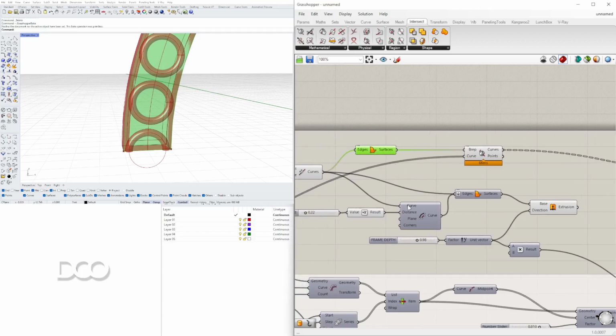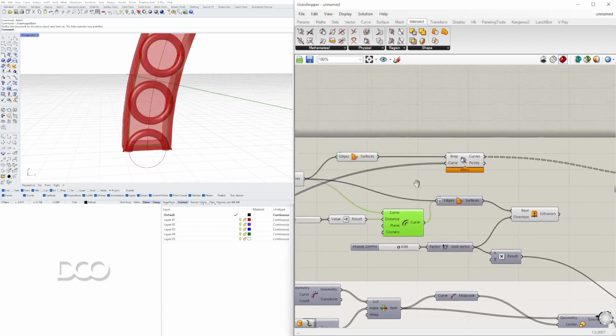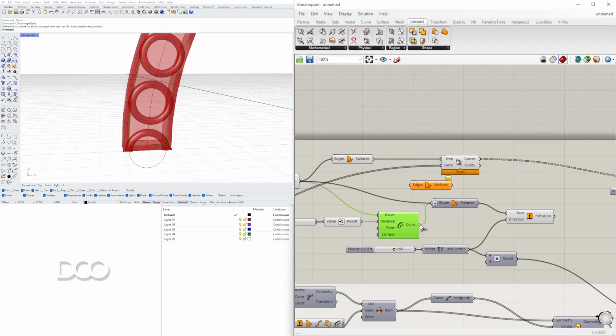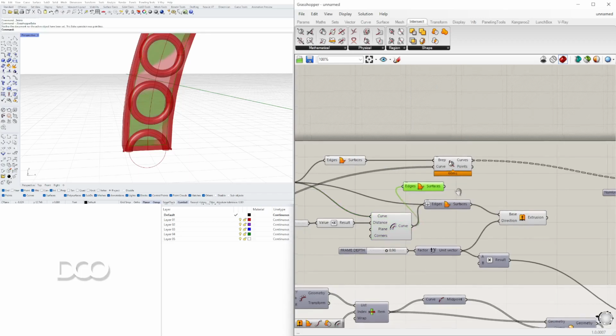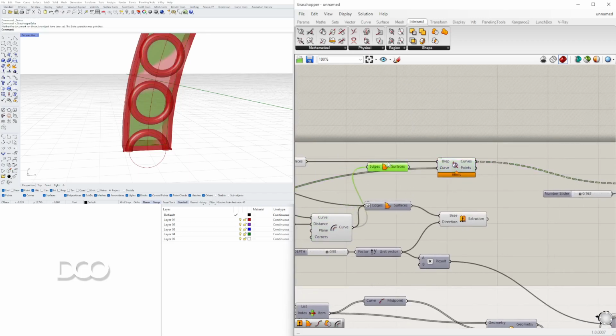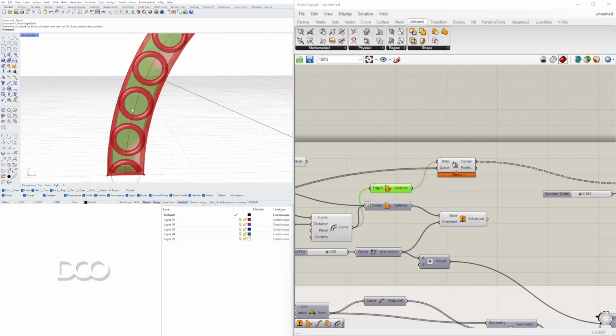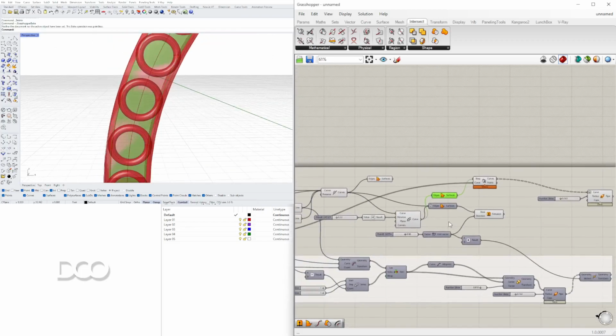So after that, we had offset it to the inside. And so if I use that, so if I go here to boundary surfaces and create one on the inside frame and use that as my intersecting surface, it actually cuts it off and it basically fixes the issue that we had.